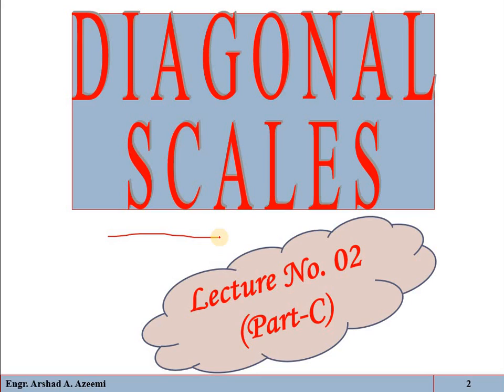This is most important: being an engineer, whenever you are drawing a structure or any plan or map, you will have to express the scale. The better form of expression or representation of scale is the graphical form. Then we have different types of graphical scale, like the plain scale and the diagonal scale. The plain scale was discussed in the second part of this lecture, and now we will discuss the diagonal scale. Let's revise the plain scale.